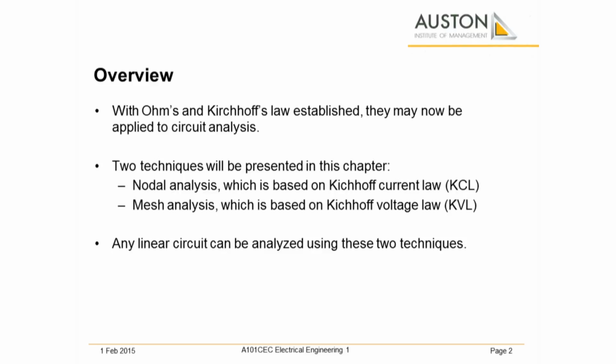One is nodal analysis, which is based on Kirchhoff's current law or KCL. The other one will be mesh analysis, which is based on Kirchhoff's voltage law or KVL. Take note that any linear circuit can be analyzed using these two techniques.